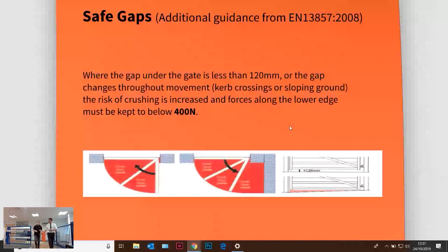So that's protecting your sweeping area, but you still need to protect the hinge point. Sometimes the laser can do that for you. It's just down to how your distance is. And obviously you've got safety edge that normally gets fitted to it as well. Not as well as the X guards. You either fit X guards or safety edge.